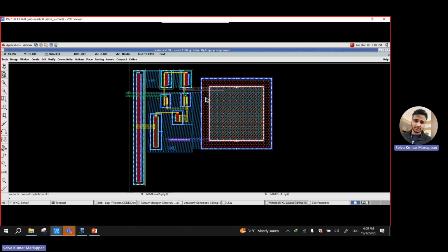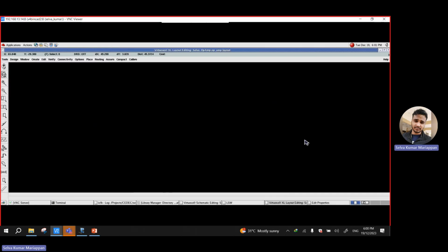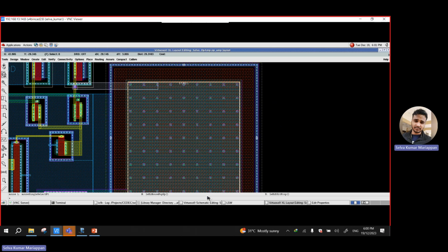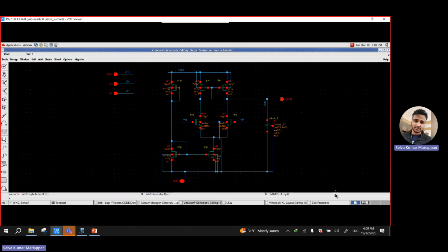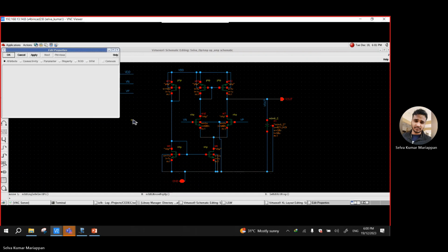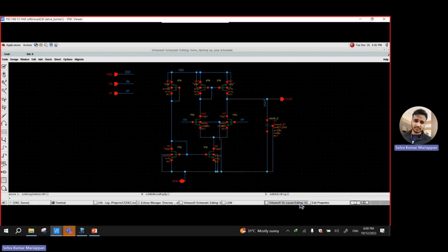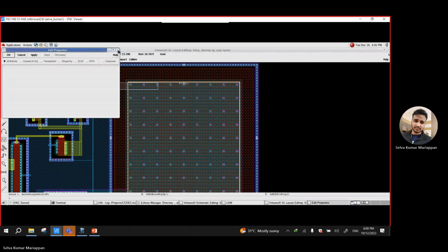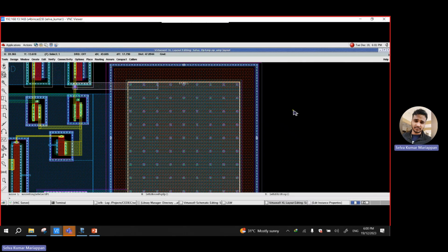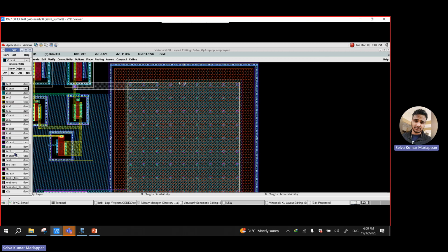And we also have our output. Our output is metal 6 from the capacitor top, correct or not? So this is where our output is, V out. You can go to your layout. I can draw one from metal 6 top.